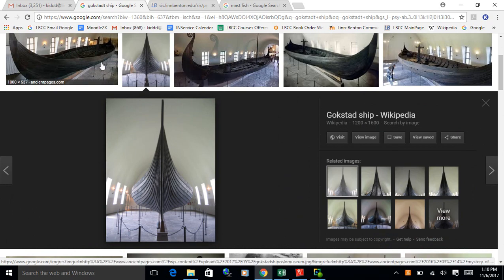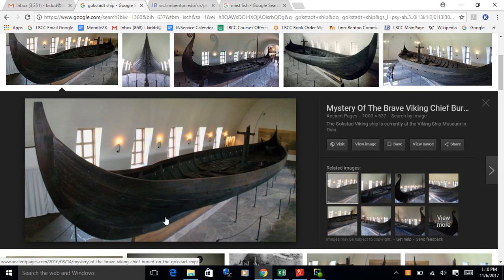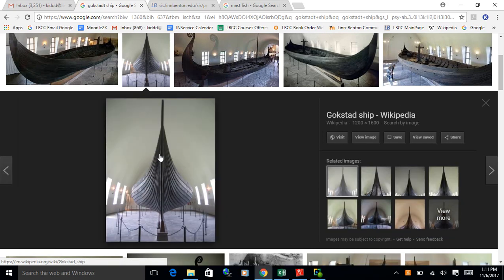And then you can see the design on the hull. They got a nice keel in there, so these things can go across the ocean, but then they broaden out quite a bit, and they can go up rivers too, which, there's just nothing in Europe that could keep up with these things, that's for sure. You got ribs in there, and then they use what they call lap strake construction. So they don't have real heavy planking as a framework. The hull itself is a lot of the framework.